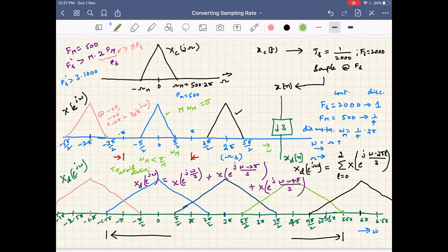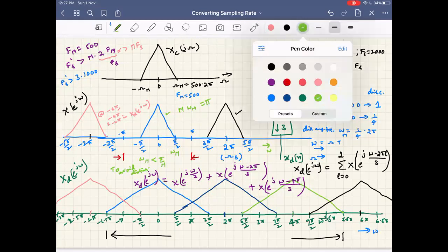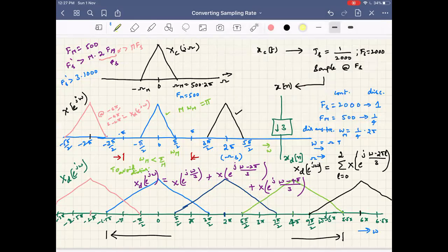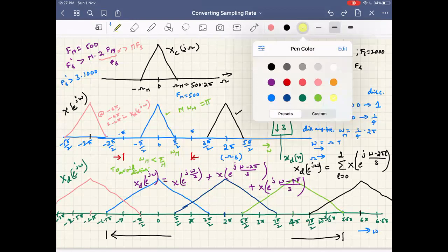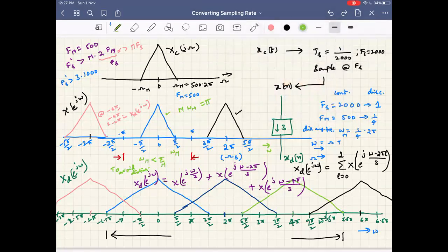and remaining frequencies, anyway, you know that they get aliased or mixed with other frequencies. So to avoid aliasing, what we can do is have a filter initially in the discrete frequency domain, for the discrete time Fourier transform spectrum ranging from minus pi by 3 to pi by 3. So that will help us to avoid aliasing.